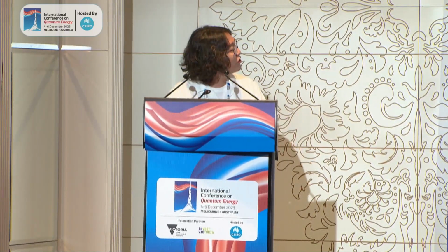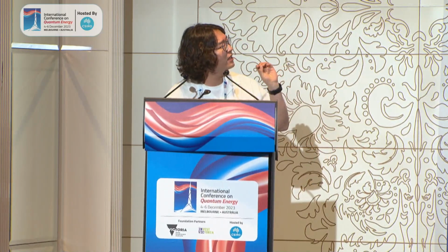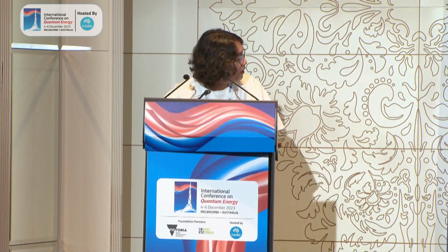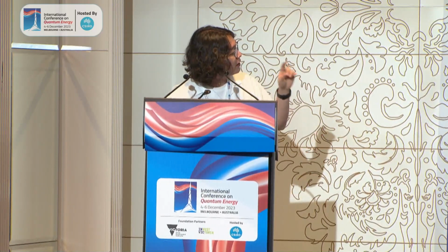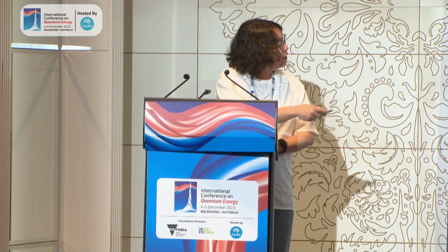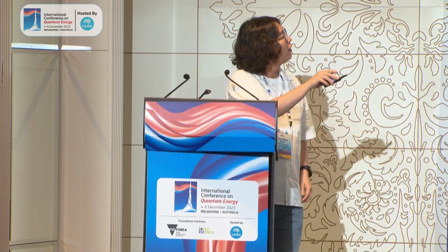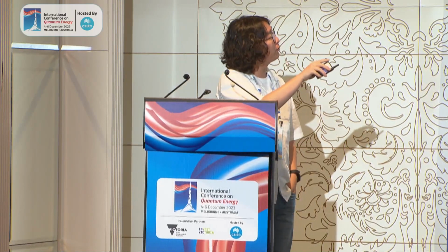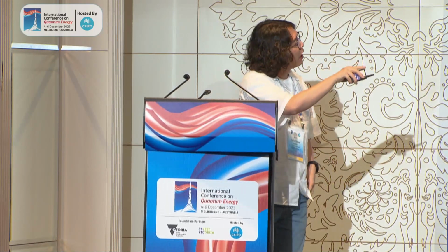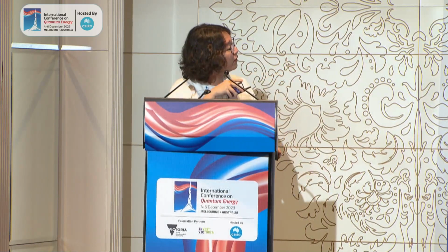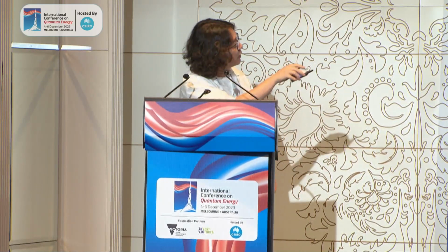Here, basically, we can consider charge below 0.1 as the anode. So if you can see here, maybe I can show you. This is the contour plot of charge less than 0.1. As you can see, for the 6 volt, the dendrite growth problem is not a big issue. However, as the potential increases, you can see that the dendrite growth is more active. So you can check the shape of the dendrite here.